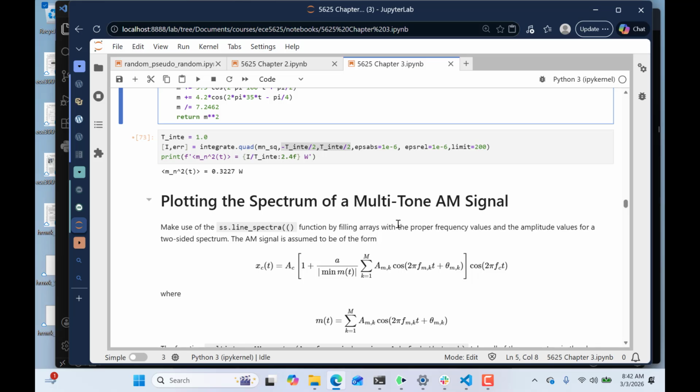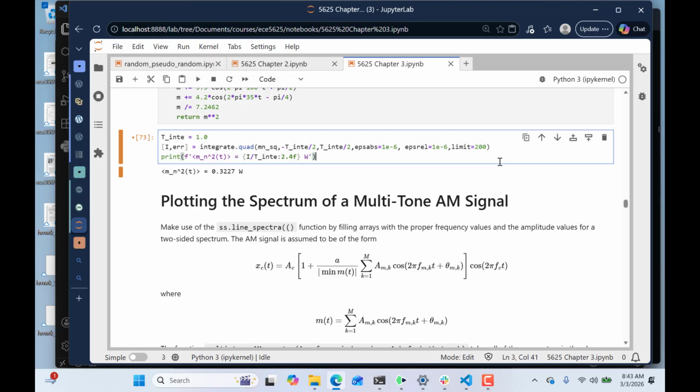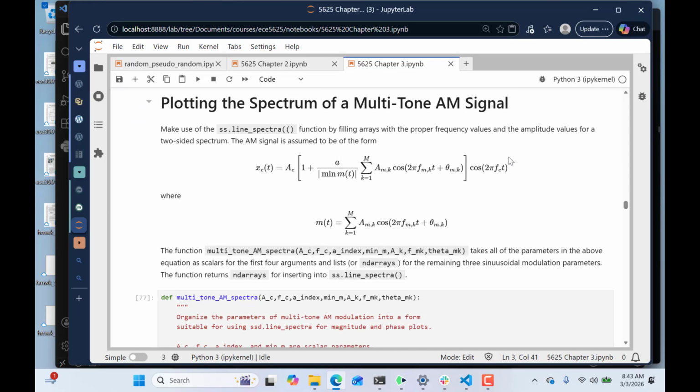I'd love to say go play with it, but play with it in your spare time, which I know you have a very limited amount of, but you may bounce into numerical integration. What I do in my work, I mostly just do the simulations like we're talking about. A simple rectangular integration, which is very easy to set up without using the integrate package, and then maybe use the power spectral density estimate to get the fractional bandwidth. I didn't have you do that in the homework problems that you just turned in, but we could have also done that too. I mean, that's just quicker, and typically it's accurate enough. But this is always at your disposal if you wanted to get more sophisticated.